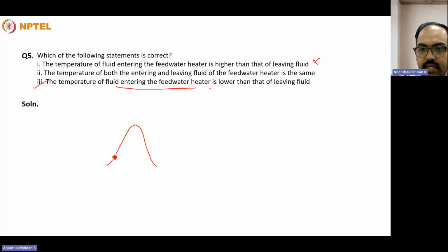So what I meant to say is that these two mix together at this particular temperature. The enthalpy of vaporization in this process will be delivered to increase the enthalpy of the pumped fluid. So T5 will be greater than T2.